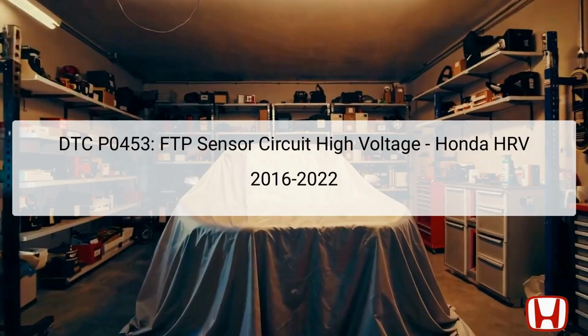The Diagnostic Trouble Code, DTC P0453, signifies an issue with the fuel tank pressure, FTP, sensor circuit, indicating a high voltage condition. This component plays a crucial role in monitoring the fuel system's vapor pressure, which is essential for preventing fuel evaporation and maintaining emissions control.